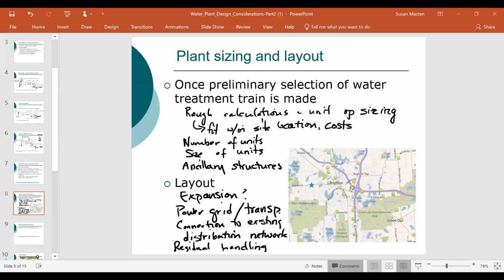East Lansing has basically drying lagoons, or dewatering lagoons. So they pump that sludge out to these large lagoons. The water evaporates, and then when there's a sufficiently high solids content, they excavate the lagoons, and then they sell off that material as land amendment.